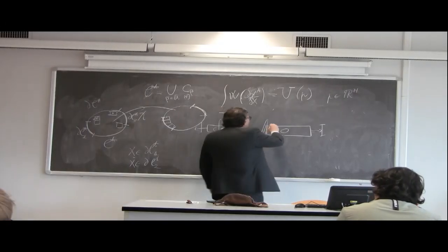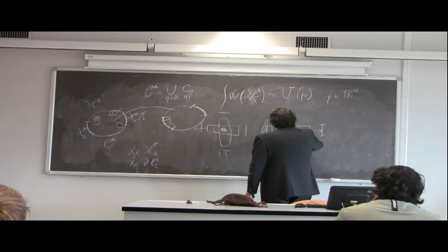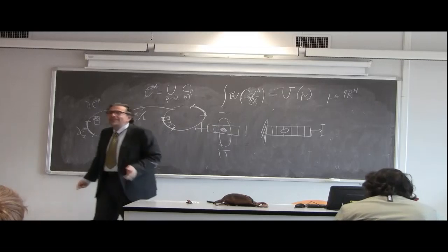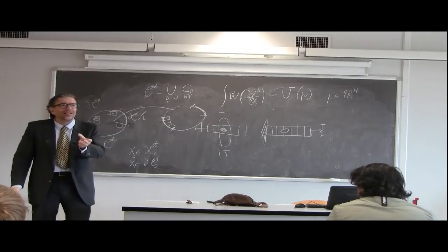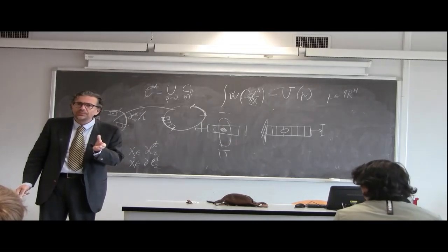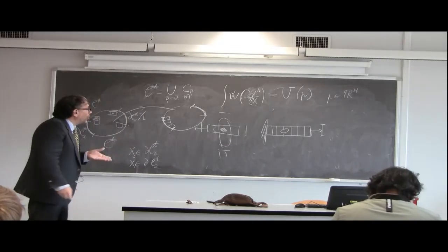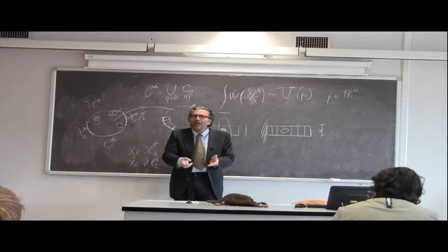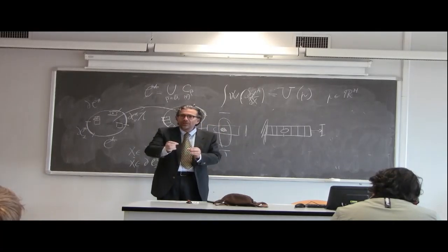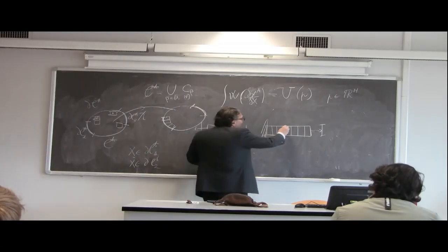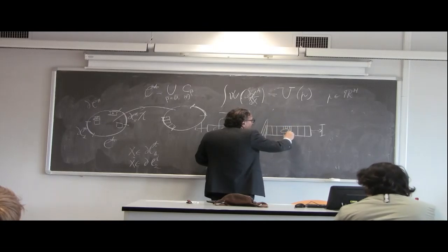Do you think that this mesh is good? This mesh is not refined enough to describe what happens around the hole. So maybe I'm trying to explain to you why we may need a mesh having different elements of the partition of different sizes. Maybe it is better if we do this way.